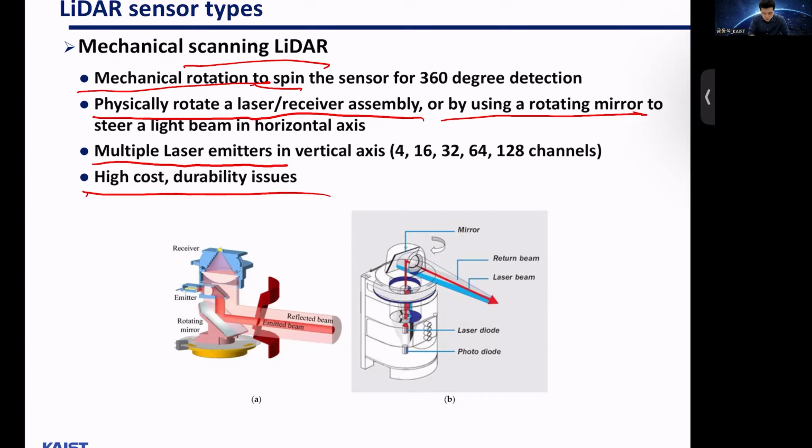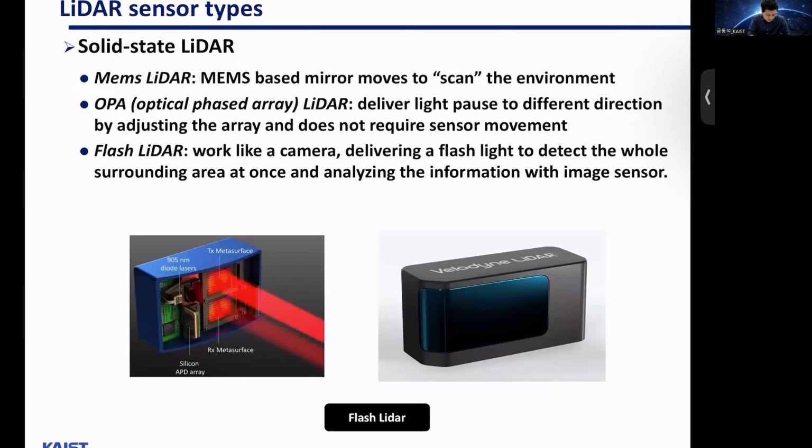So these were some of the critical issues for vehicles using LiDAR, but there are new, more robust LiDAR sensors used for automotive applications. To mitigate these problems, there are other LiDARs currently being developed, and people usually call them solid state LiDAR.